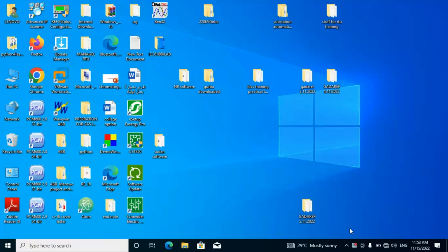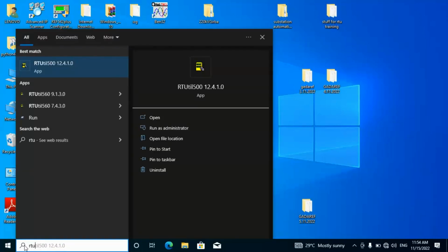In today's video, we will see what the steps are for preparing an RTU file configuration using IEC 61850. The RTU type we are going to be using is the ABB RTU 560. We will be using the software RTUtil 12.4 to prepare the RTU file and export the ICD file, and we will see how to prepare the network tree, the hardware tree, and all those things. The version we are going to be using is 12.4.